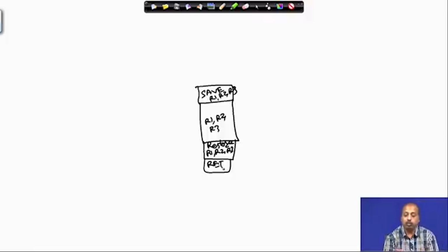Why? Because in the calling program R1, R2, R3 might have been in use. So before using those registers we should save them, and before returning we should restore them.